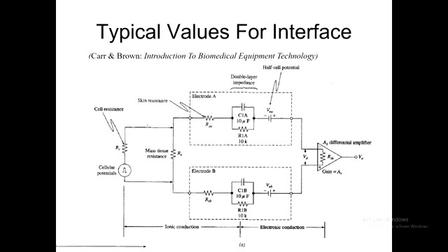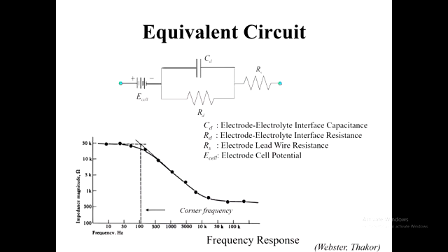They haven't told us what their frequency response is, but we would say that this is a typical clinical electrode. It looks like it would work quite well down at very low frequencies, wouldn't it? Whereas this one here is a more tailor-made one for perhaps higher frequencies. Okay? Some work to follow through.